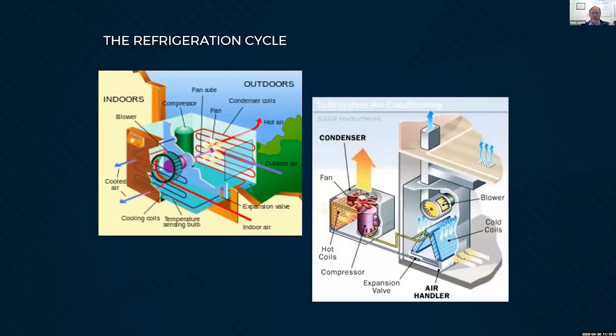Same thing happens in a split system, a typical residential split where you have an outdoor condensing unit. Basically, they've just taken this box on the left and split it into two pieces. Compressor and condensing coil, condenser fan outside. Inside, you have your expansion valve, metering device, again through the A coil and back out.